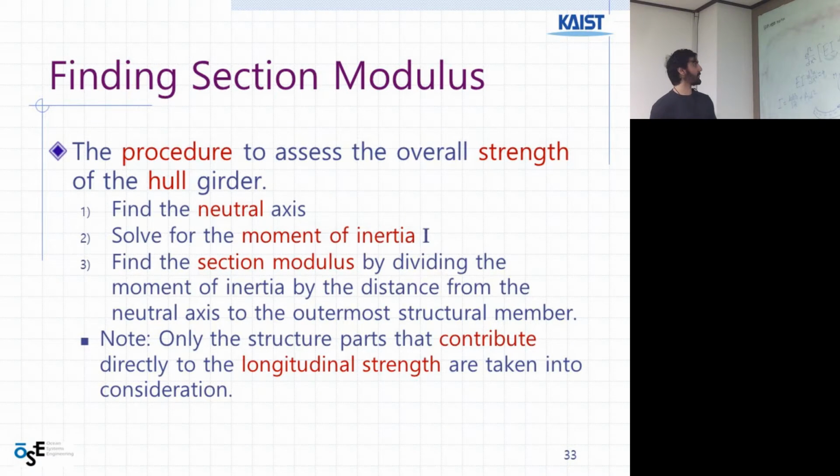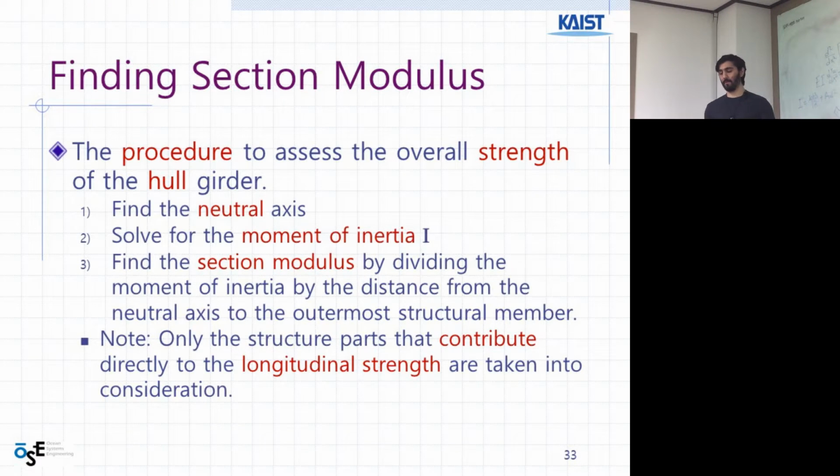So the Euler-Bernoulli equation is really important here. Now, the worst case combination of loads. In order to predict the maximum bending moment, what are the loads? It's usually the weight and the buoyancy.